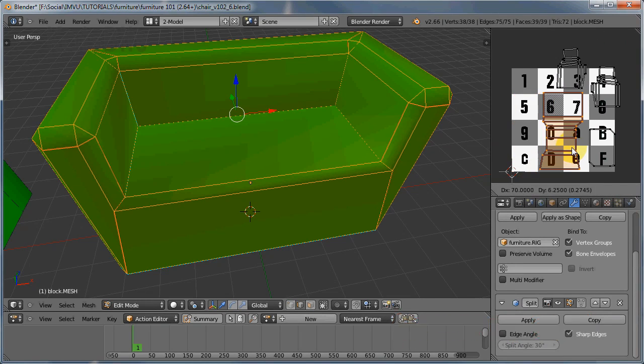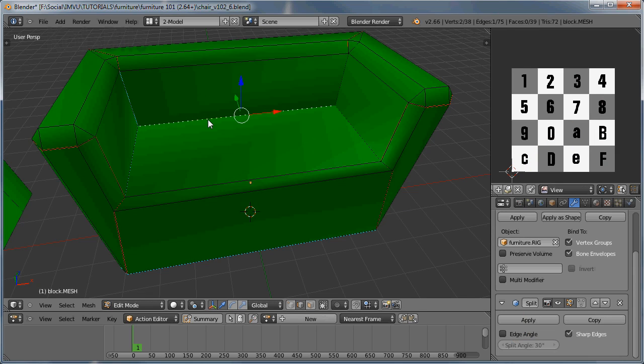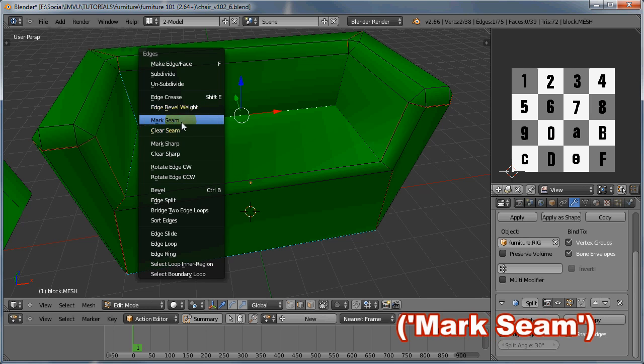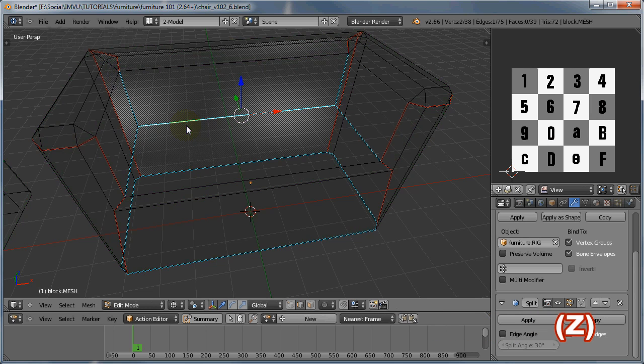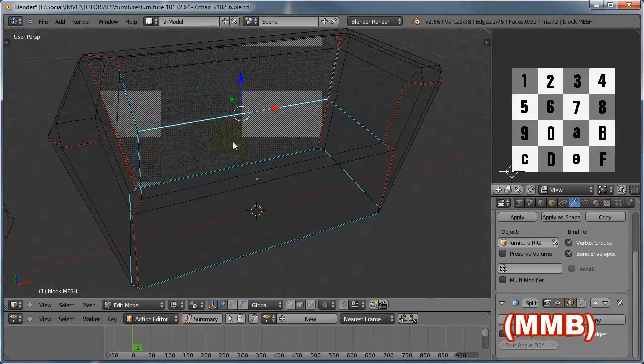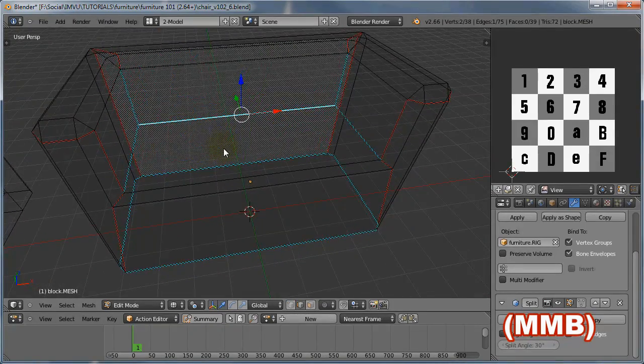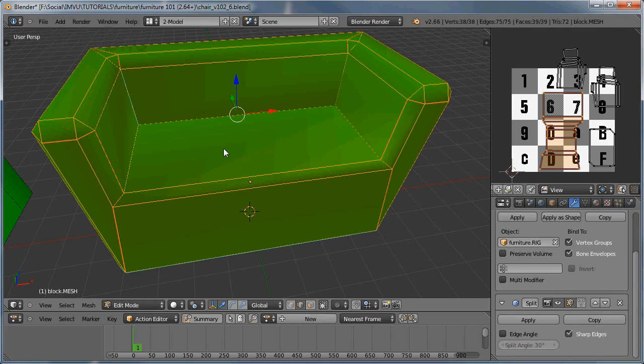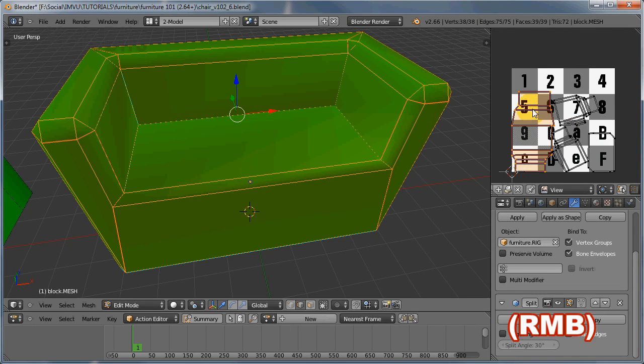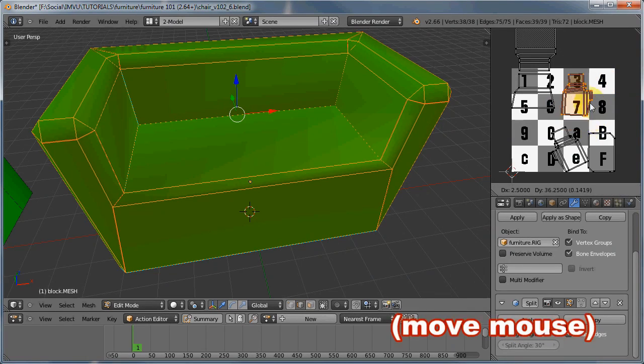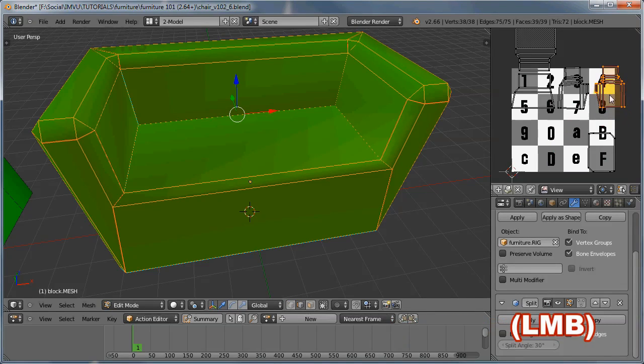Now what we've got here is the front of the mesh and the back of the mesh as one section, so we need to double check the assignment of the seam, reselect, unwrap, which results in splitting the one UV section into two separate parts. Select, rotate, and continue to reorganize the sections of the UV map so they fit within the texture space that's available.